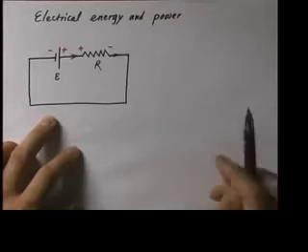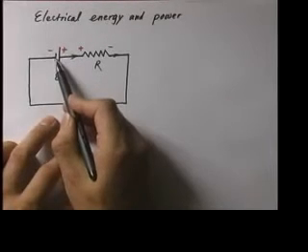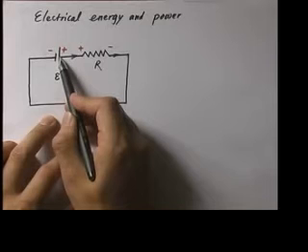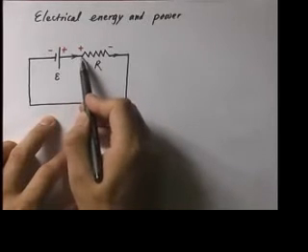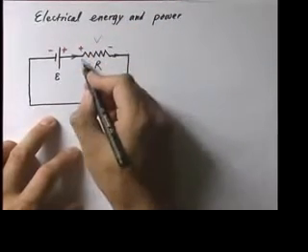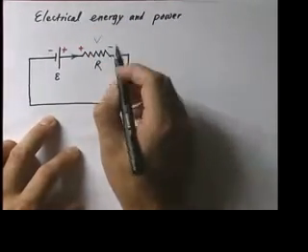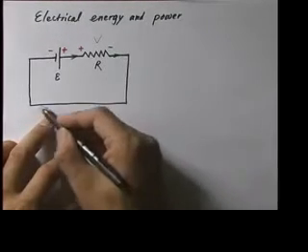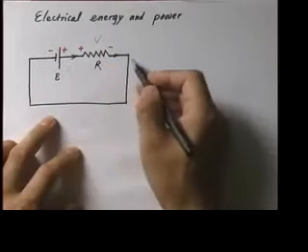Same deal. Okay, so we start from here, right? Let's say the potential here is zero. We can define this to be zero. We go up to epsilon, which will bring us to that point, and then we have to go down. Let's say the potential difference is V from here to there. It drops by an amount V, and that will bring us to this point, which has the same potential, because that's just a conducting wire.